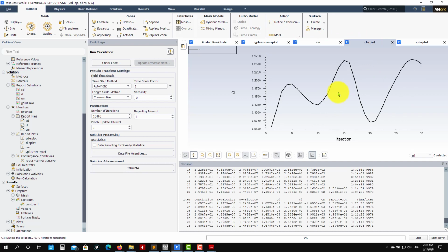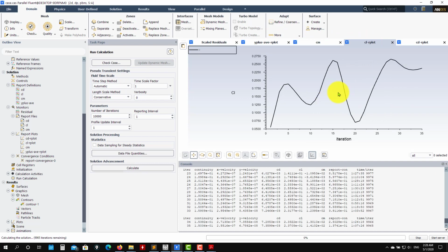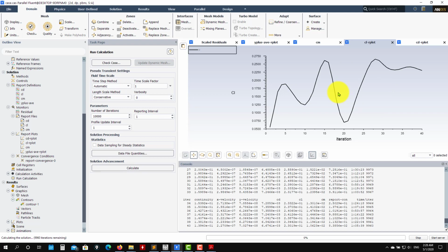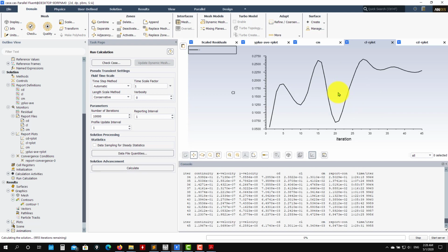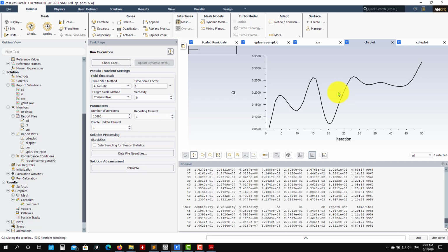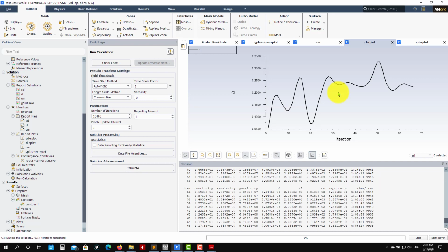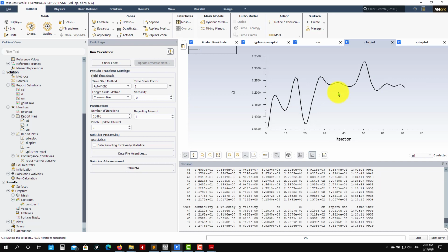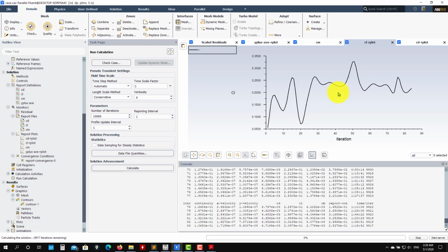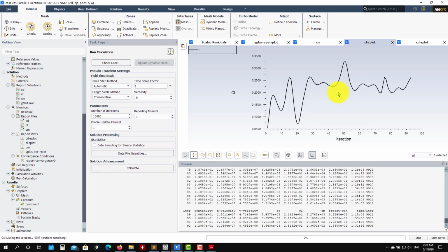Okay, so the scope of all these turbulence models is that additional quantity that we need to add to make it physically realistic. I'm not saying that what we're having here is not physically realistic, but remember that if you do without turbulence models, that is DNS, you are solving the exact Navier-Stokes equations. So you need very fine meshes, and you need to work also unsteady to capture all scales.